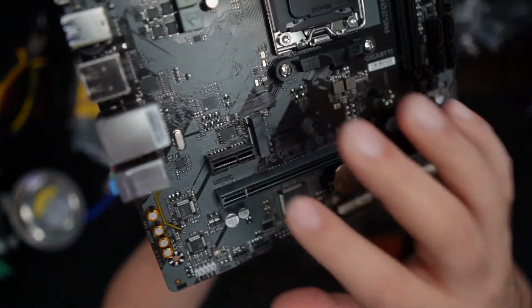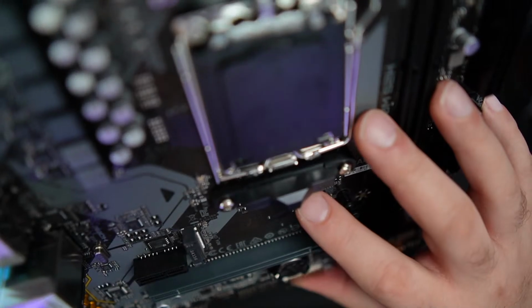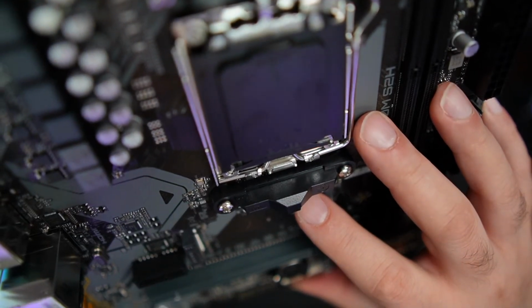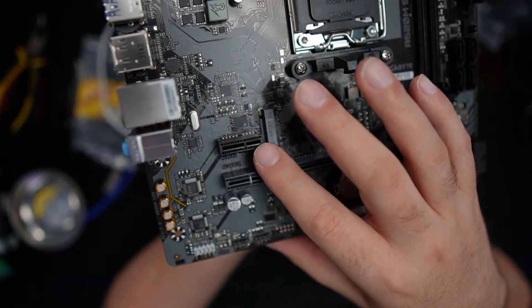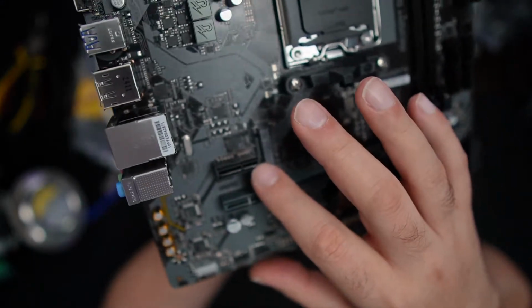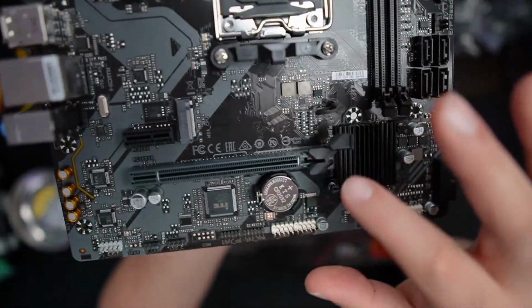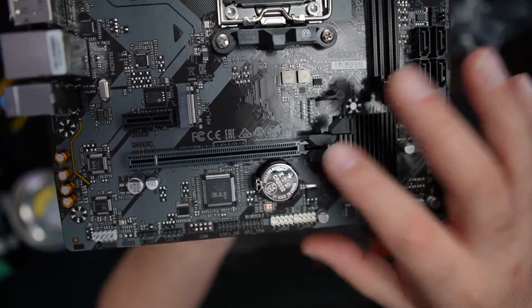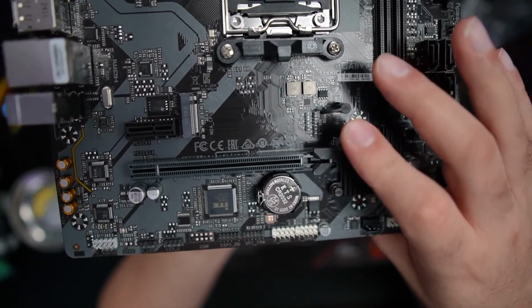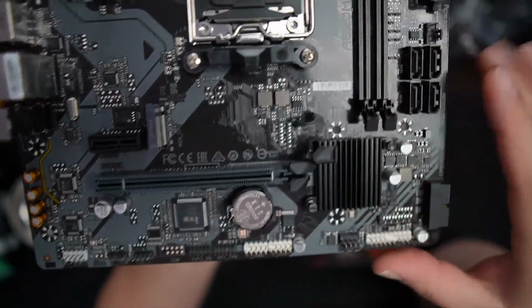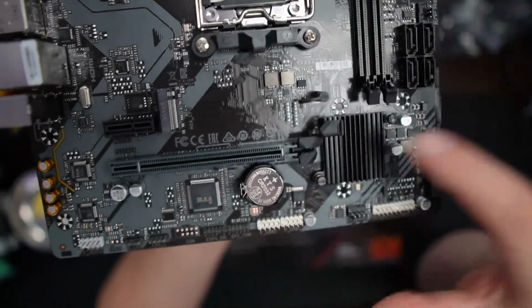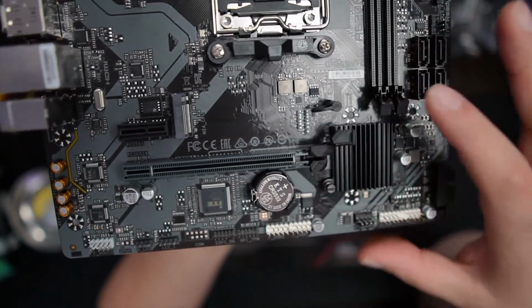PCI Express sockets. I think you have a 4 socket. Can be a 4 socket. So right here is 4 or 1, depending upon what you're putting into there. Your graphic card itself will go into this socket here. I'm going to push this down so it's in the open position. When we go to put the graphic card in, it will click back into a lock position.